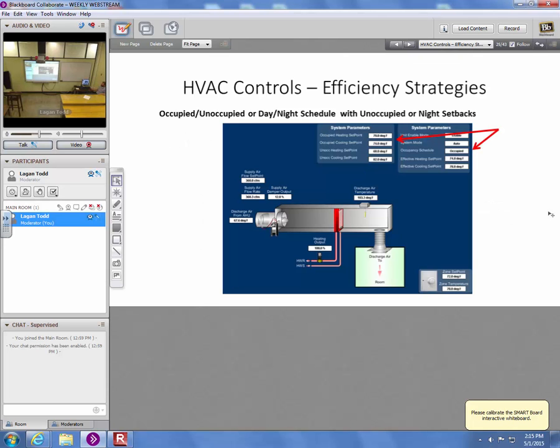And here you can see a screenshot from the front end user interface for a building automation system. This equipment here is what's called a variable air volume terminal unit, or VAV box. Let me just tell you what this thing does first, to get the context. Somewhere upstream of this is a big air handler, and the air handler feeds tempered air to this inlet. Let's say it's delivering 65-degree air that has a certain amount of ventilation outside air and a certain amount of return air. It's mixed air, 65 degrees, which is what we call kind of neutral air.